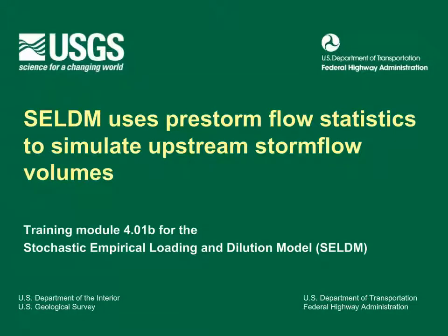This training module is an overview of methods used to simulate pre-storm streamflows as part of the upstream stormwater volumes with the stochastic empirical loading and dilution model. We use the term pre-storm flow rather than base flow because the streamflow at the beginning of a runoff event commonly includes runoff from a previous event.